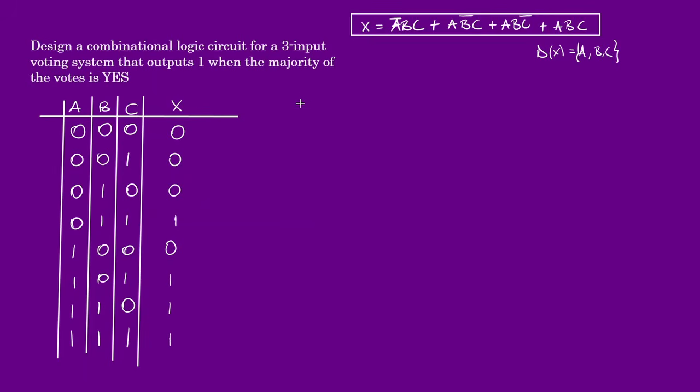So let's see if we can get our hands around not A, B, C. If we say this is the line for A, this the line for B, and this the line for C, we need to negate A, so we'll make this a negation. And perform the AND operation on 3 of these simultaneously. So that's going to be a really big gate.